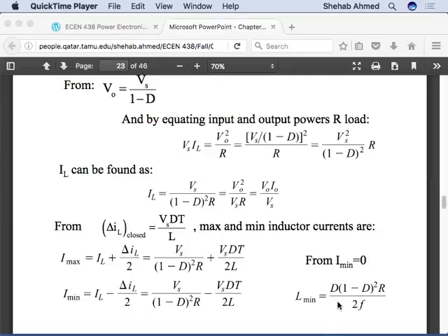Again, typically your first design iteration will be without losses, and then you will do a more detailed analysis. You do that because you want to select your switches, and you want to select your ideal inductance and capacitance values. Then you will start considering losses. Then you will start considering dynamics, right? So it's several stages. We're learning about the first stage, and we will also learn about the second stage by calculating the losses. We will talk about losses specifically later in the chapter.